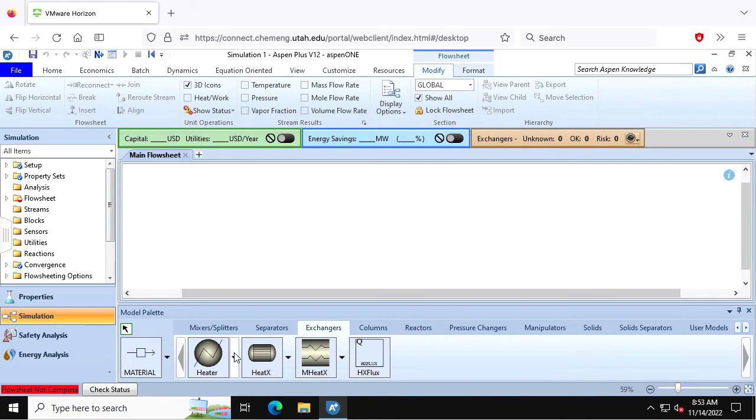And because of that, you have slip around the impeller. So as you increase the flow rate, and particularly the discharge pressure, that slip increases. So it's not exactly linear in terms of the performance. So that's why it curves over.